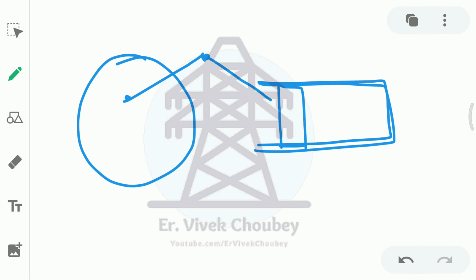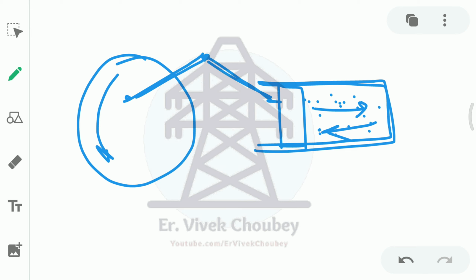Inside this cylinder there is a piston. Now this wheel that you are seeing rotates, and as it begins to rotate, and this rod is hinged, this piston goes forward and backward. This is called reciprocating movement. Due to this reciprocating movement, the refrigerant which is converted into gas fills up here, and this piston compresses it. Because it moves in this direction and there is no leakage, this gas is completely compressed and is converted into liquid refrigerant. So that's how a compressor works.